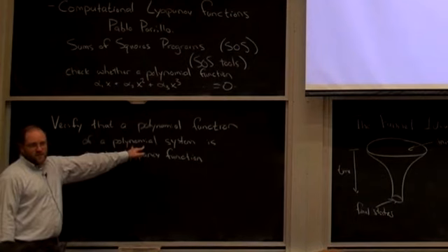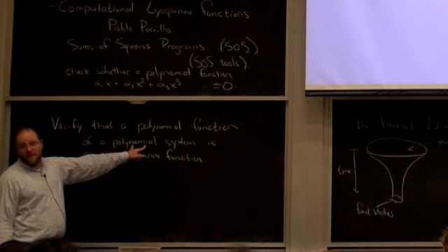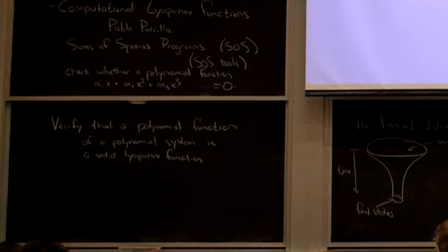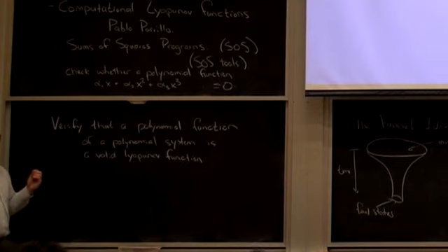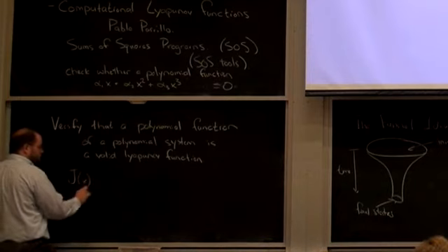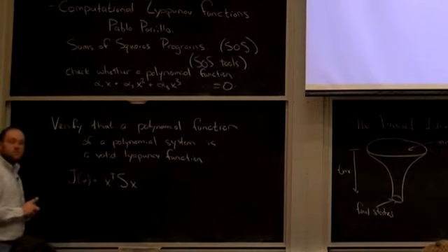I threw this one in without saying it before. The only caveat is you have to take your nonlinear system and make a polynomial approximation of it, a Taylor expansion of it. It doesn't have to be first order, that's the linear system, but it has to be polynomial. So it turns out that for the LQR systems, remember our value function, let's just think of the LTI LQR. The value function turns out to be this quadratic form.